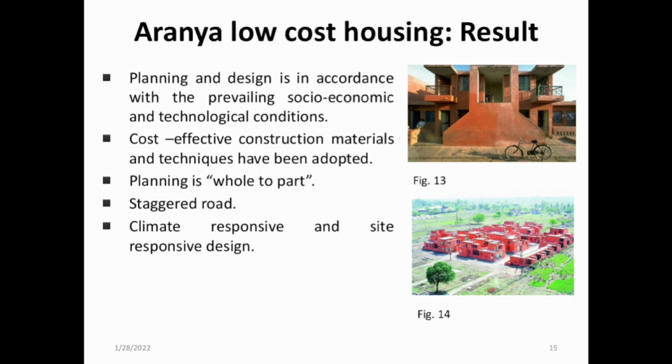Planning and designing was in accordance with the prevailing socio-economic and technological conditions. This project adopted cost-effective construction materials and techniques. In this, planning was whole to part, that is from township level to dwelling unit level. Accessibility was an essential factor for designing in this project. Staggered roads prevented through traffic and reduced the speed of vehicles. It had climate responsive and site responsive design.